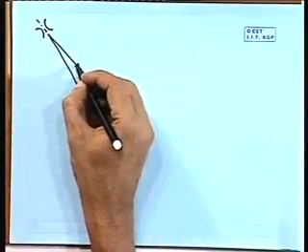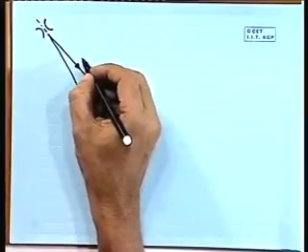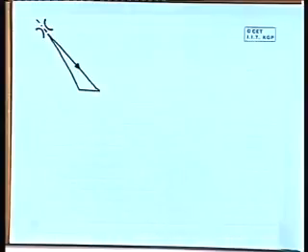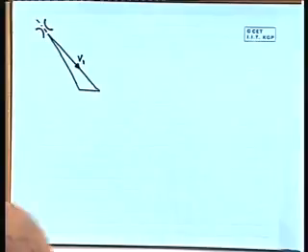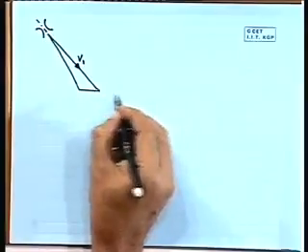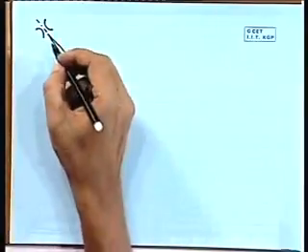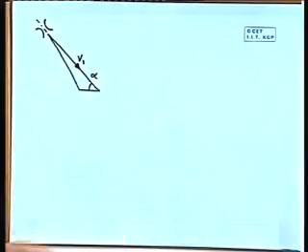So, this will be the absolute velocity of the steam coming out of the nozzle, and obviously, this is the absolute velocity of steam which is entering the blade passage, and this is represented as V1. Now, this direction is the direction of rotation, and let us say the nozzle makes an angle alpha with the direction of rotation. So, we can say that the absolute velocity of steam makes an angle alpha with the direction of rotation.